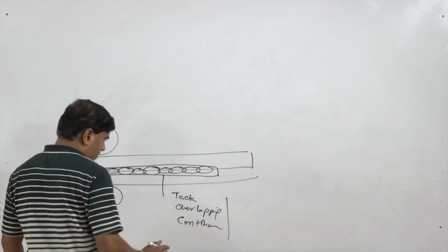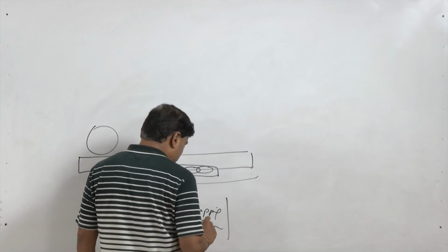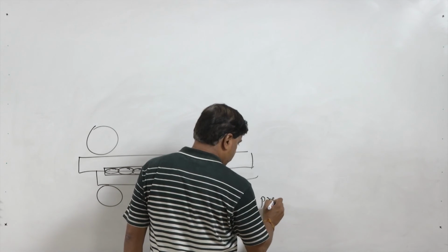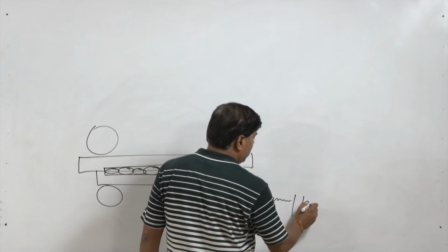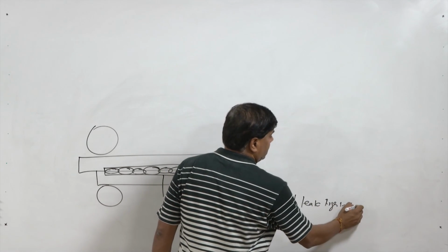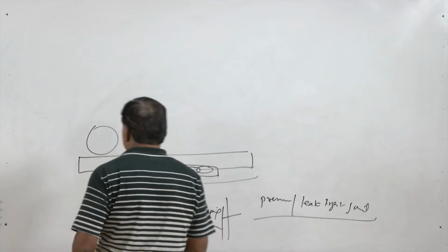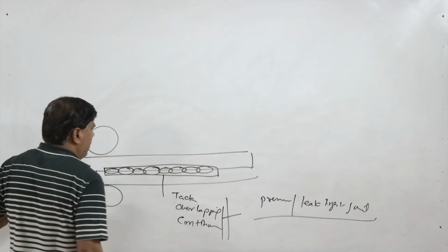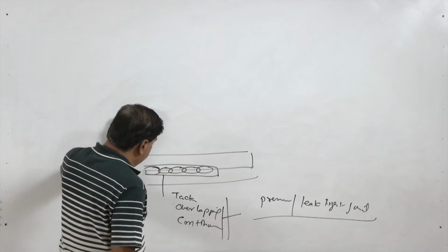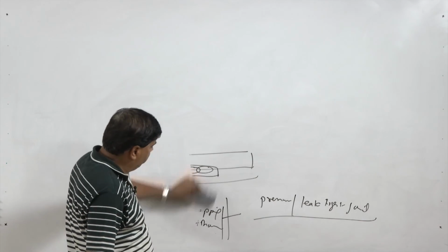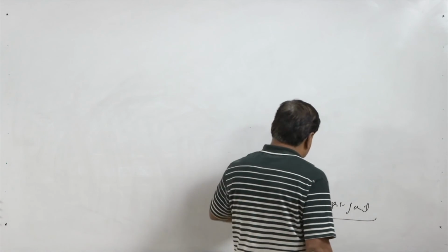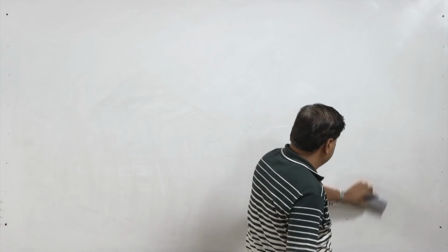The continuous or overlapping type of seam welds are normally used for making pressure or leak tight joints of sheets, mainly for tanks, and wherever it is required that the joint is leak proof, the seam weld is made. That also works in the same way, on the contact resistance heating principle.